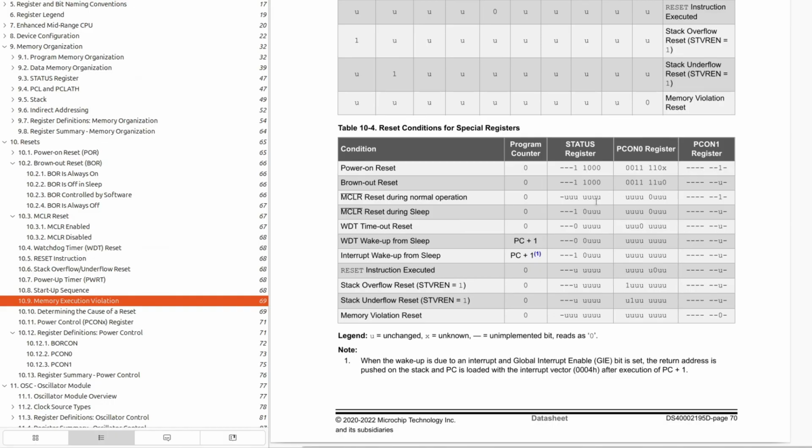So one thing that we can do is write some code that as the device starts up, it will display the status of those 2 registers, wait a little bit, and then continue on its way. And during that wait, we can view the status of those registers to determine why the last reset was caused. And depending on the pattern that gets displayed, we get some hints as to where to go to solve our problem. So you can see why we're going to need a timer to hold that information on the indicator display before it continues as normal. But we're going to need more than a timer.